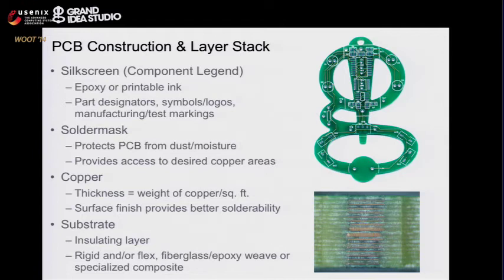Substrate, copper weights, there's all sorts of different variations of circuit board fabrication. So some techniques are going to work better than others depending on if the board is simple or if it's highly integrated with lots of layers. Here's a 16-layer board. One of the examples I use is an Apple iPhone 4 16 gig board. It's a 10-layer, less than 1 millimeter thick board. It's insanely complex. So I use that as the state of the art.